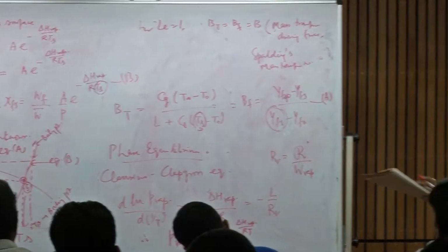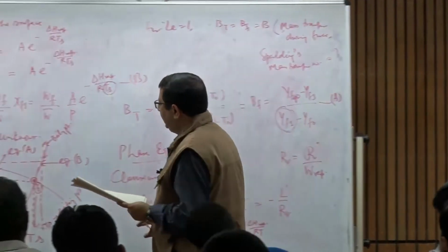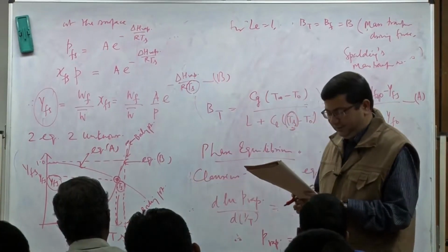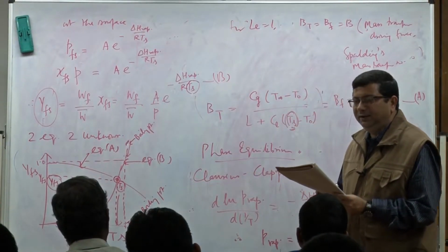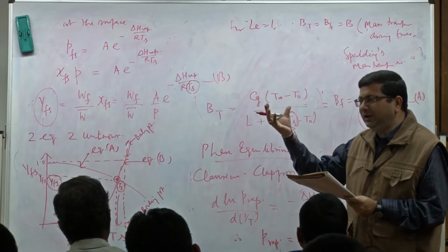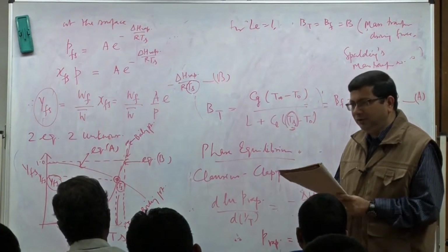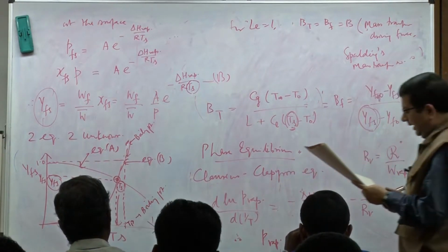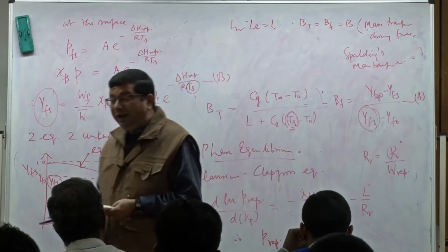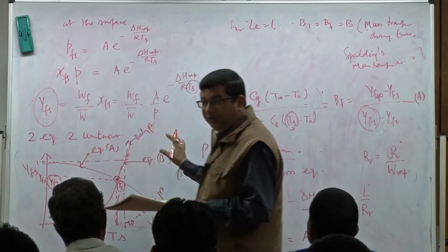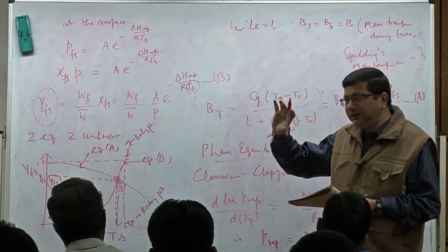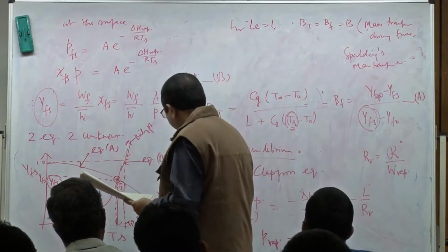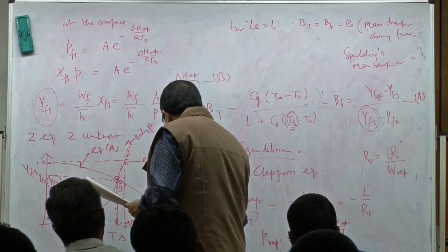So, essentially what we see from this is the surface temperature is below the boiling point for the burning liquid, okay, because if it reaches the boiling point there is immediate complete evaporation. Okay. So, surface temperature is slightly below the boiling point of the evaporating liquid. However, when it happens in a combusting environment, typically the ambient temperature T infinity is very high.